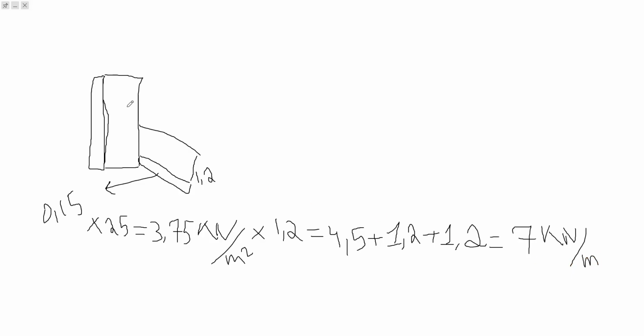And we have to also find the loads of this landing slab, and apply the total of this 7 with this landing slab load onto the landing beam.